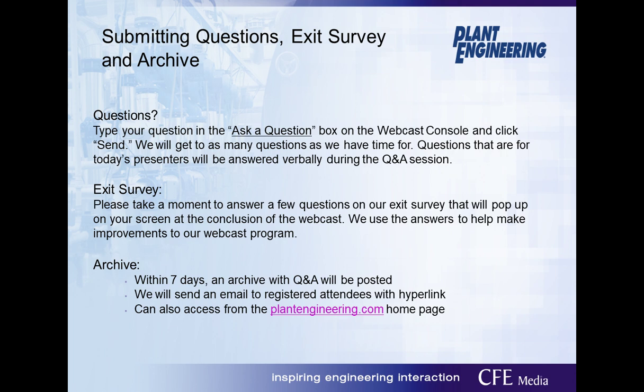On modulating machines, you have to estimate the volume of the system and then do a pressure decay on the system. Again, these are some of the things that we do in the Compressed Air Challenge training. But my point is, it's really key to understand how much you're using at those times where you're using absolutely nothing, and to then be able to put it into dollars.